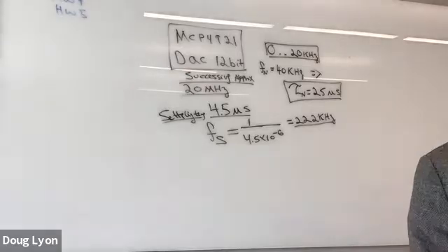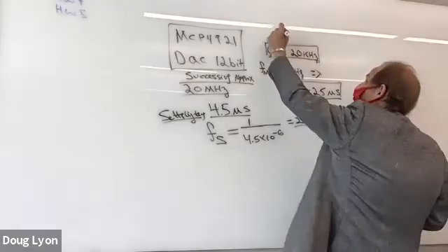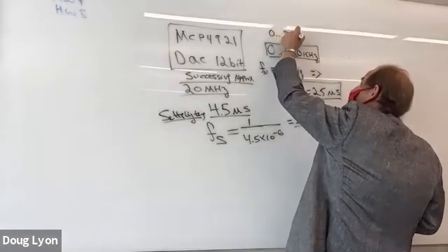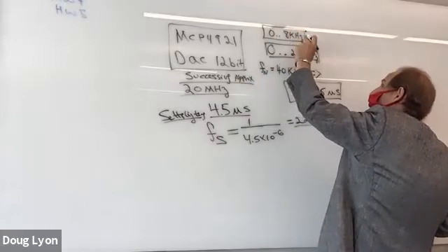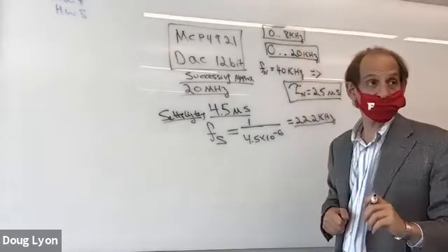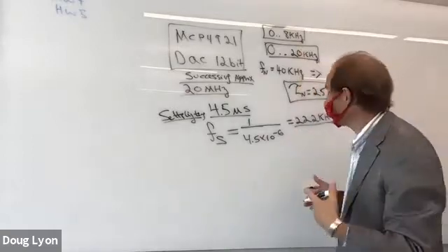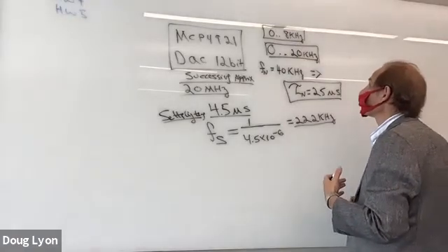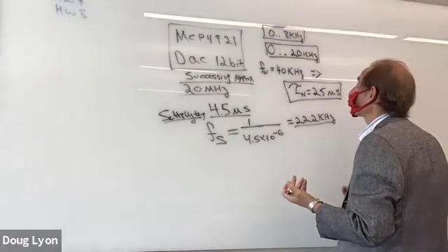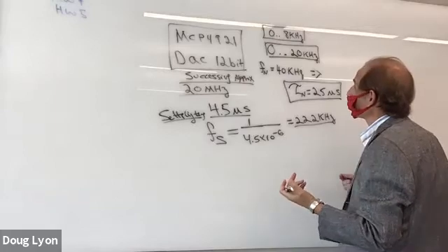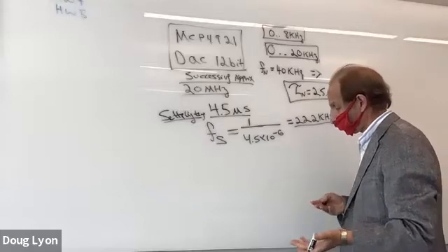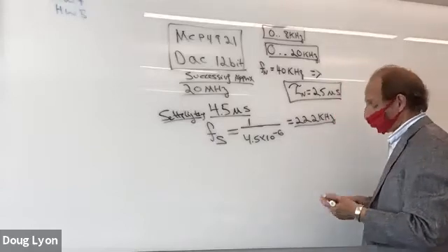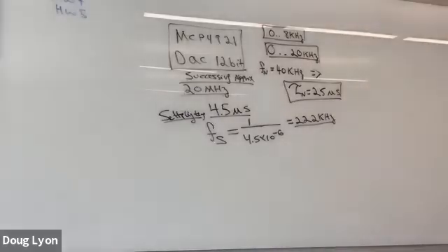In fact, if all you wanted to do was voice, you could go from 0 to 8 kilohertz. That would be the bandwidth for, we'll call it a voice grade phone line. And so if all you want to do is record your voice, then in principle, you could probably stop with a sampling of 8 kilohertz and just go from 0 to 4 kilohertz on your maximum output. Most of the energy is going to be in the lower frequencies anyway. So if 8 kilohertz is all you really need for your sampling,